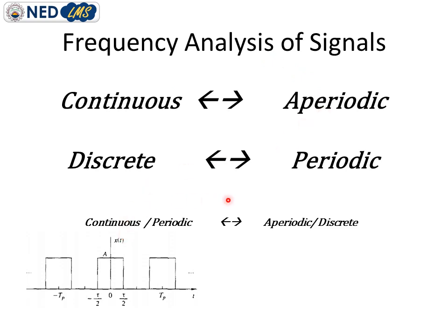Fine. So we have to write aperiodic here. Second thing is periodic. Your signal is periodic, and for periodic you already know that the spectrum must be discrete, so you have to write discrete here. By knowing these two parameters, you are actually predicting these two parameters. Your waveform is continuous. Continuous means the spectrum would be aperiodic, and your waveform is periodic, which means your spectrum will be discrete. So I'm going to display its spectrum.